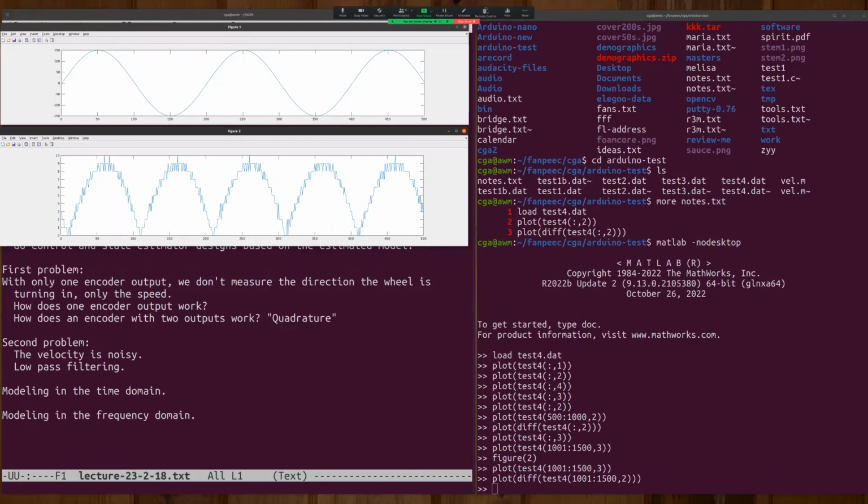And so at this point, you and I know the velocity is changing sign here. Well, what's going on? The first thing you can say is the wheel velocity pretty much looks like the motor command. It's delayed a little bit. So a reasonable model of this physical system is it's like a screen door. It's heavily, heavily damped.